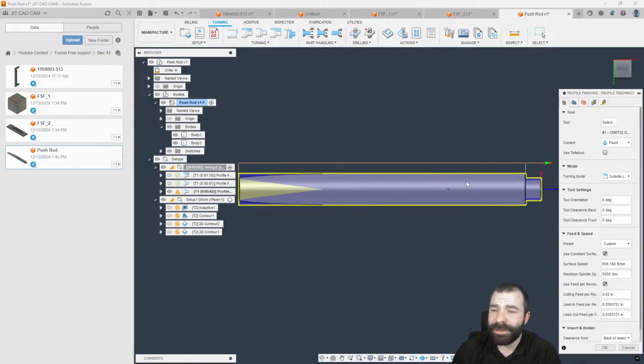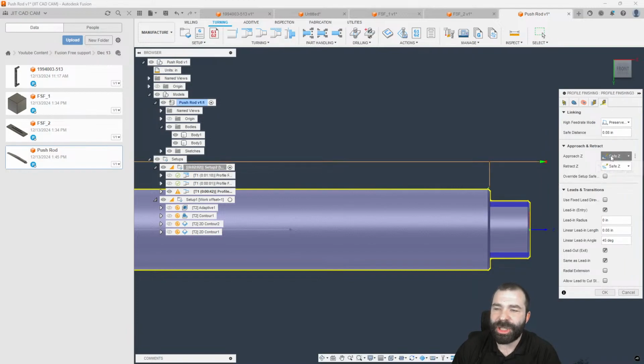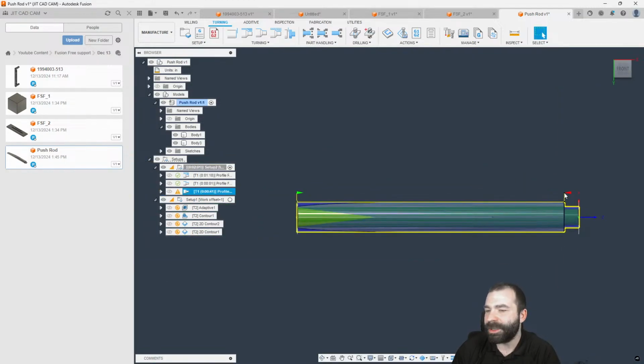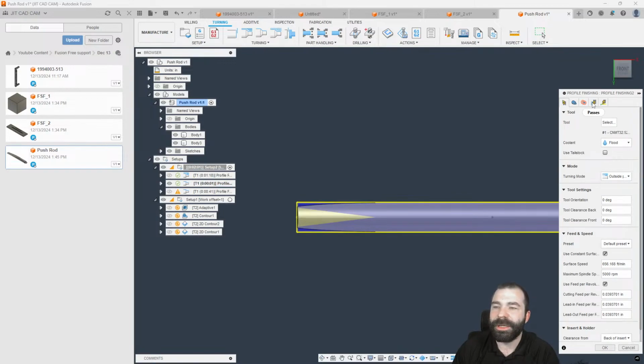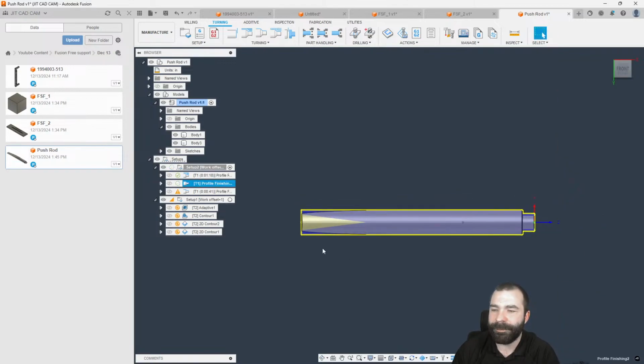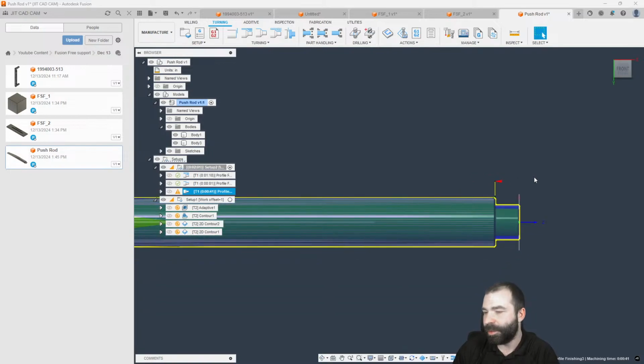Instead of having my tool start all the way out here, you guys could actually change your approach and say first Z, last tool point. And then that will actually bring your tool in. As you can see, it will start from this position and come out here without all that additional rapiding movement, right? So if you're really looking to speed up some cycle times, we do our first and our last point. And again, now you're going to see we come down and around and out, and then immediately we could jump right into that next tool path and go down that shaft.